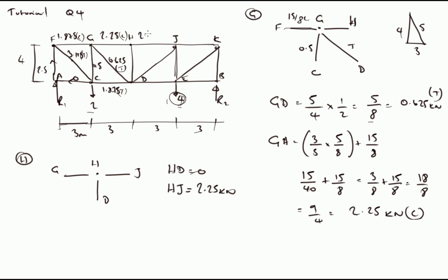So this is 2.25 also, and that is compression as well. Any load compressing on H has to be balanced by another load compressing from J to H, so it's in compression.